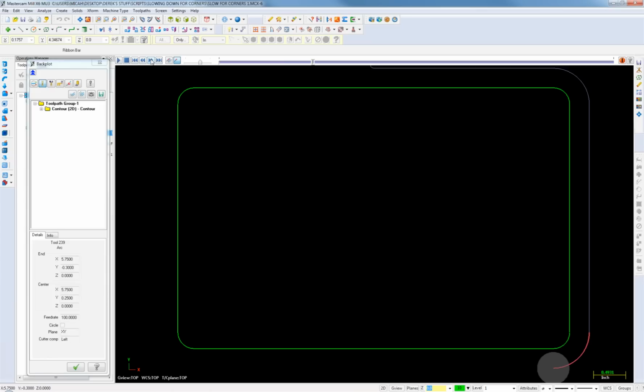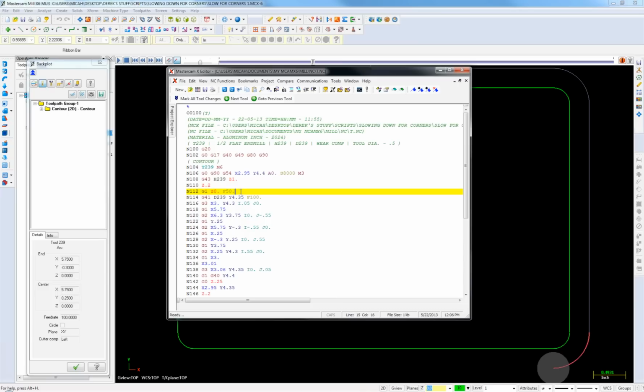With an older machine especially, it will be difficult for it to maintain accuracy while trying to cut the arcs at full speed. If the goal is to have a good-looking part, then that's not a problem. But if we need to hold tight tolerances, this issue could leave us wondering just why parts won't fit together. While we can simply change the feed rate in the toolpath editor after posting this operation, this can be tedious and cause errors if we're not extremely careful while editing.